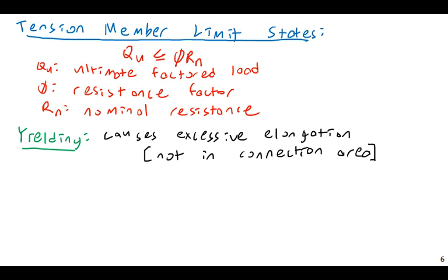A lot of the materials we like to build our buildings out of are fairly brittle. We have a lot of problems with the soils in Houston, the expansive clay soils, and because of that you often get large deformations in your foundations.